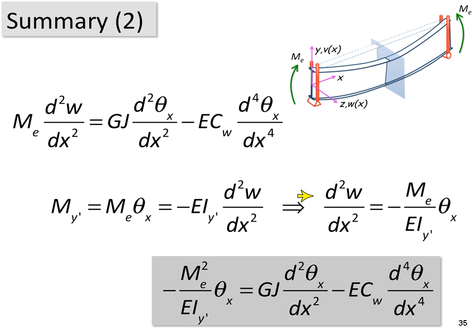And we can now make a substitution for this term right here and for this term here, and we end up with this. Now, why is this great? Well, finally we've got a differential equation that is all in terms of theta x. So we've got theta x, the second derivative of theta x, and the fourth derivative of theta x. Where before, when we thought we were at the end, two of the differentials were in terms of theta x, and the other one was w. So this last little dance provided us with a nice, happy differential equation.